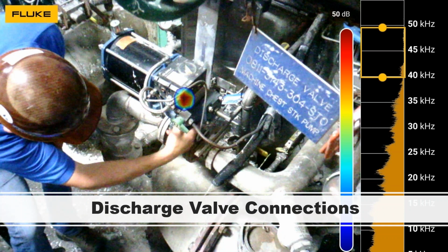Discharge valves. Now, interesting things. You're going to know by the kind of facility that you have whether something is a specific device that's meant to be discharging on a regular basis, or it's not meant to be. If it's a normal exhaust, of course it's going to be blowing off air, blowing off some kind of gas. But sometimes you can sit there and actually watch the cycling of the device too to make sure it's working properly. If it's supposed to go on a certain pattern and it's going all the time, that's a problem.